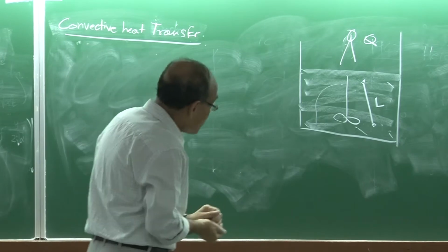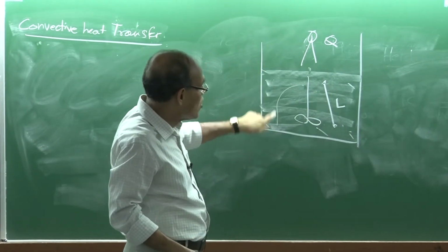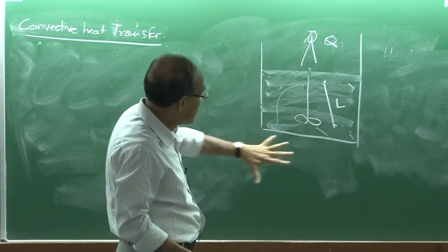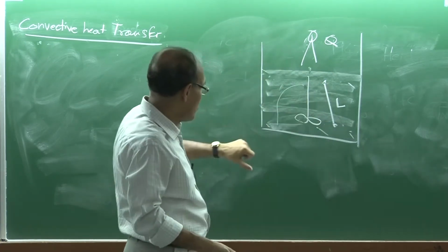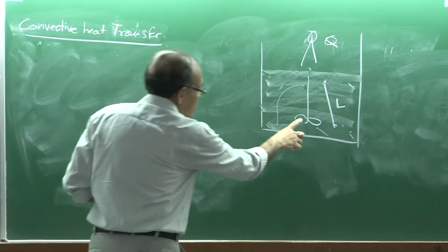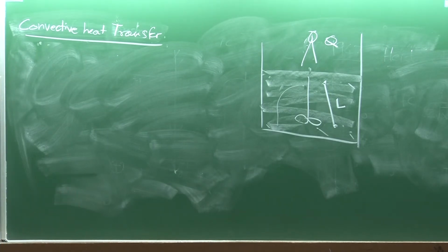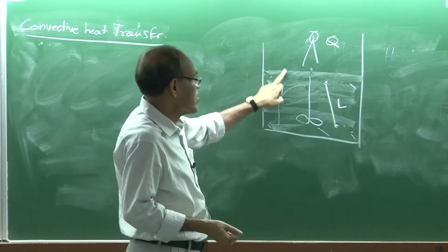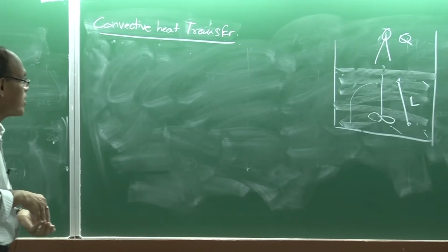But the point I wanted to make here is that from the surface, heat will take an enormously long time to get distributed over the entire system. To expedite the transport of heat, or to get a homogeneous liquid metal containing a uniform temperature, what is needed is stirring in the system. The stirring will expedite the flow of heat. So, if you want to transfer heat over a large distance, you have to resort to convection. There is no other shortcut to it.